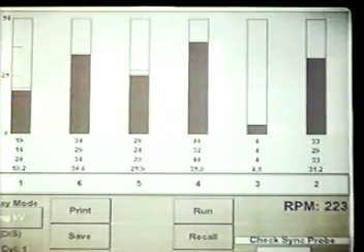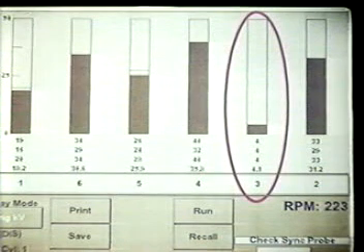Now let me run by you a formula here. The law of ionization tells us that it takes 80 volts of electrical energy to force current flow across a 1,000th inch air gap. So if we have no compression, like in this example with a 45 thousandths gap plug, you can do the math. It'll tell us that under zero compression, in other words, atmospheric air, it will take roughly about 3,000 to 3,500 volts to overcome that 45 thousandths inch air gap. So if you look at cylinder number 3 here, you can see the minimum kV during this cranking with no compression on cylinder number 3 did in fact tell us that it only took 3 kV, meaning zero compression, in other words 15 psi of atmospheric air.